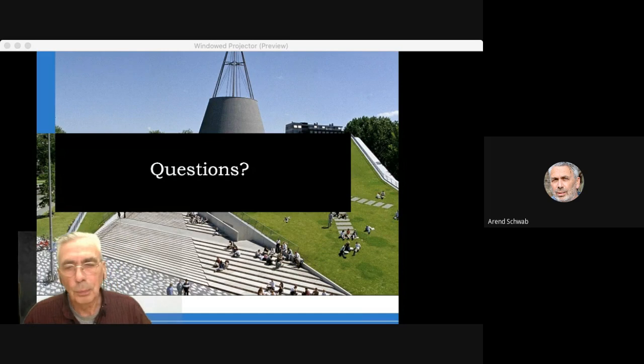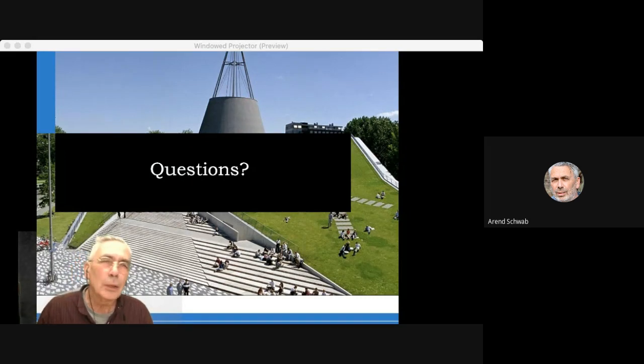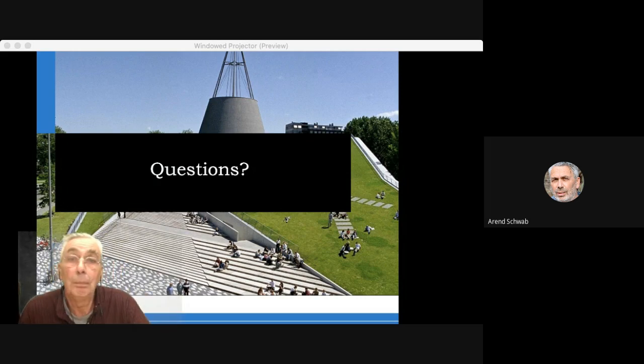Okay, we reduced this number of parameters. We have linearized the equations. Is it only about small numbers, etc.? So we went through a number of steps. The first thing was, of course, we built a full nonlinear model of this two-mass skate bike, of this eight parameter thing. A full nonlinear model that also showed this stability behavior. So then we were confident that it's not about small numbers. It's probably going to work. And of course, the next step was just to build the experimental bike, because the proof of the pudding is in the eating, right? So build the machine and show that it stays upright.